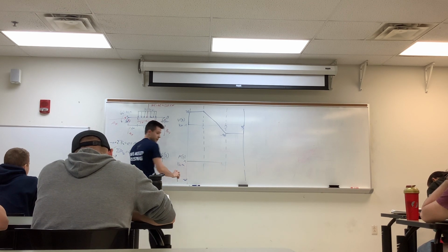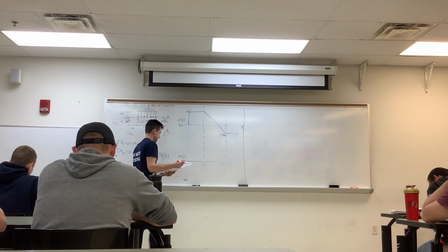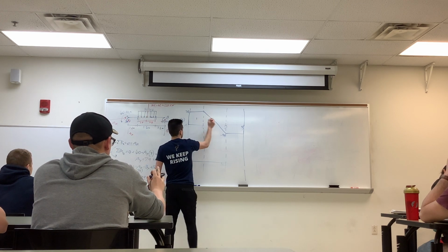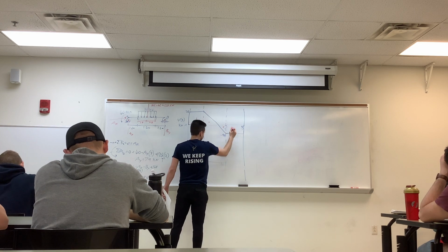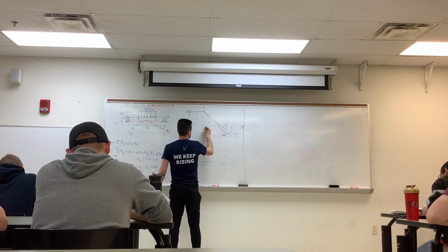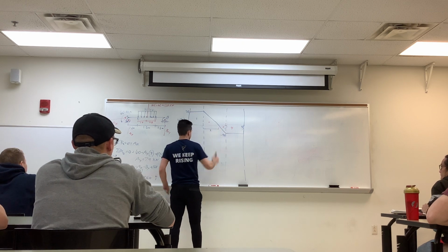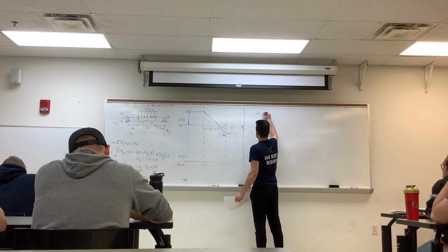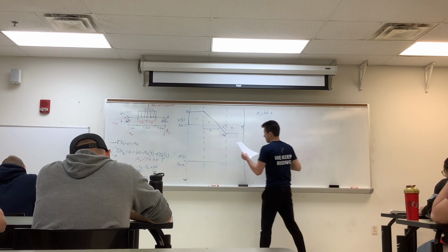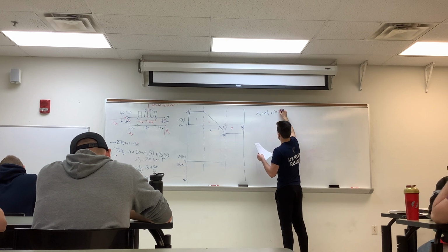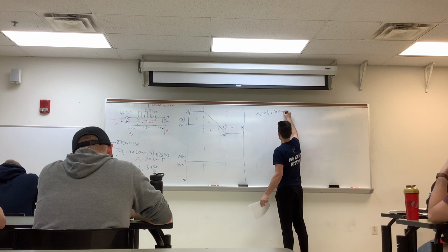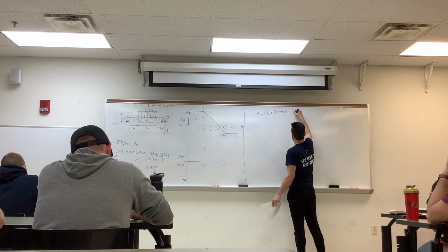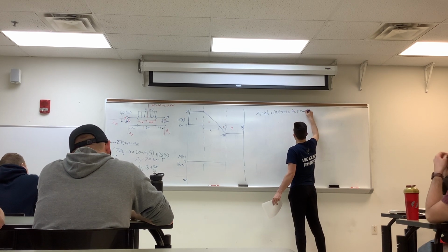From here, the change in the moment diagram is the area of our shear diagram. So we have area 1, 2, 3, 4. In addition, we have this distance of x1. Area 1 is relatively simple. It's just base times height, which is 1.2 multiplied by that 79 kilonewtons, giving us 94.8 kilonewton meters.